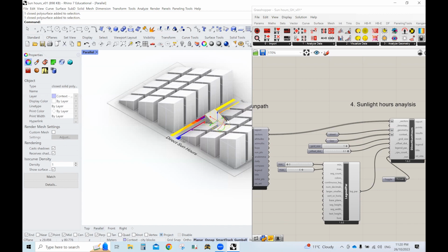So we know that this is creating a pretty accurate result. So we'll flip that back. Again, if your computer was struggling to compute this, I would turn it off and then switch the building. Generally, don't make too many changes while the Grasshopper script is running, unless it's easily handling it.